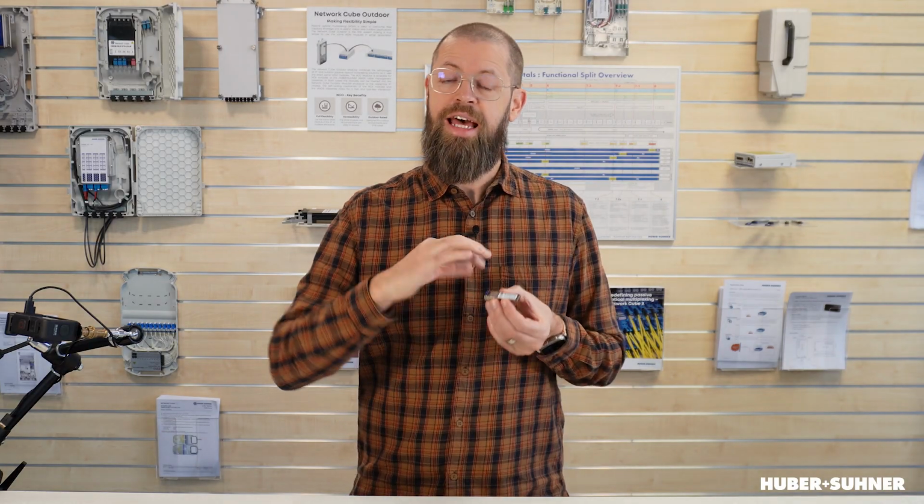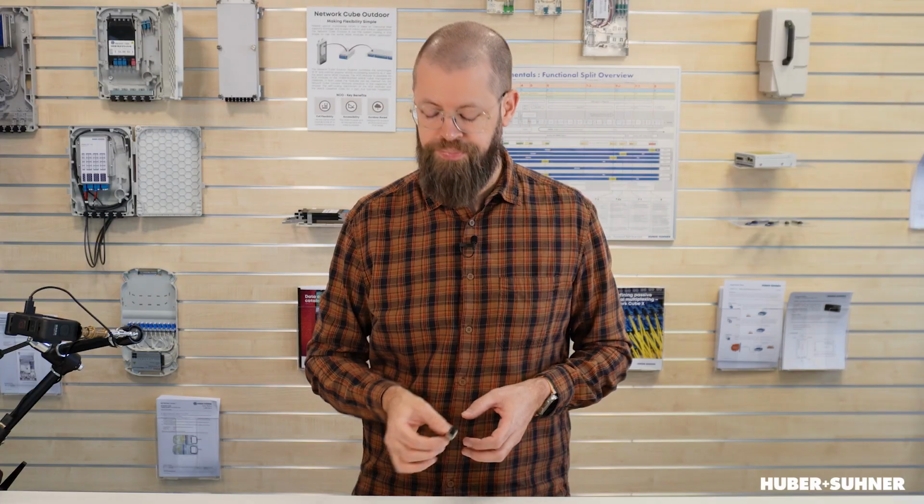First of all, we've got the transceivers with fixed wavelengths. In other words, we have different transceivers for the different wavelengths. We then also have the tunable transceivers, in other words, one type of hardware that can then be tuned to the different wavelengths. And then we also have the auto-tune transceivers, which automatically tune to the right channel when they're plugged into the system and they have their counterpart auto-tune transceiver.